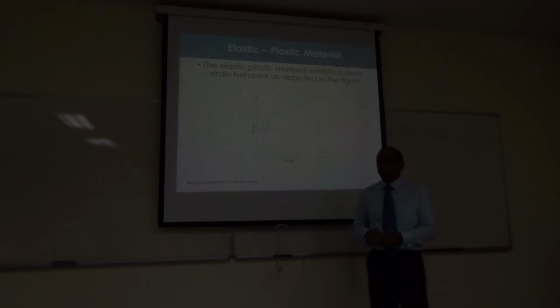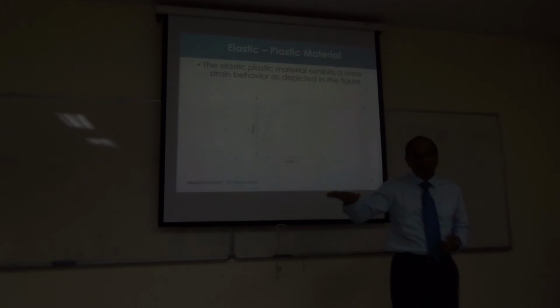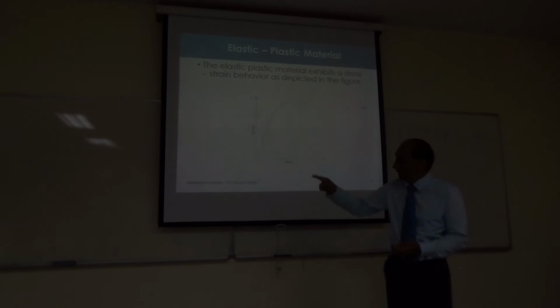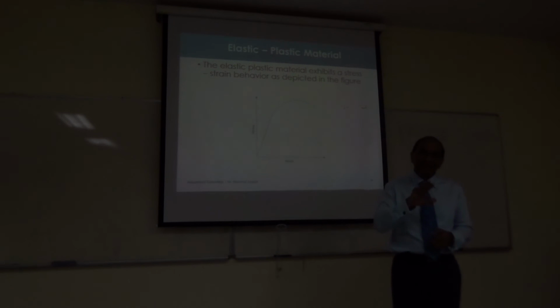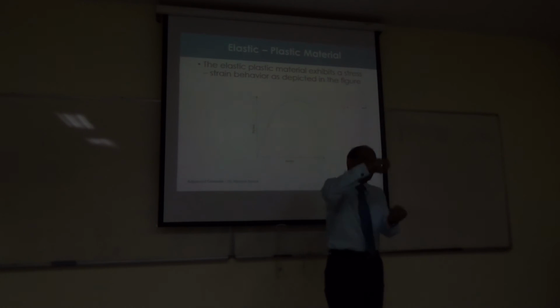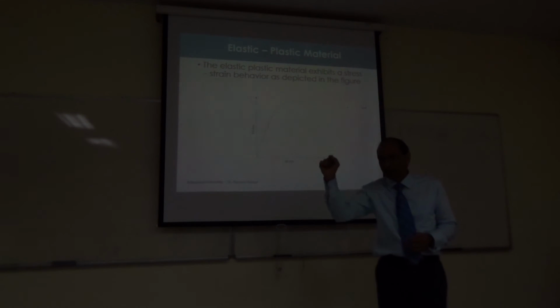So this is how basically every material can be classified into one of these 5 types, right? So for getting the material properties, if we can get the stress strain curve, we can determine most of the things that we want. And if we do a cyclic test, then we can also determine other properties that we need, right? But the problem is it must be done at different temperatures. The other things, like time dependent effects, still cannot be done. So the basic properties can be determined from the stress strain curve. That means take the material, put it in the lab, and test it until failure, and plot the points along the way.